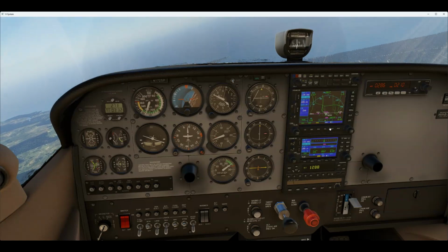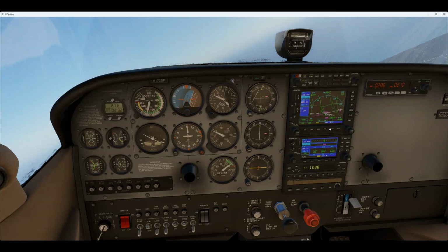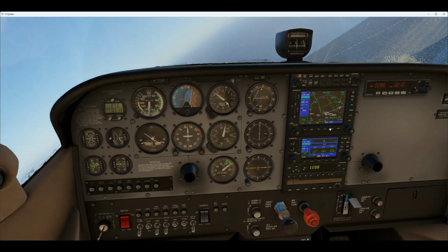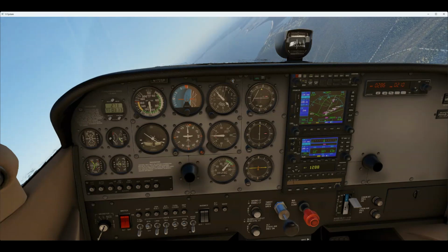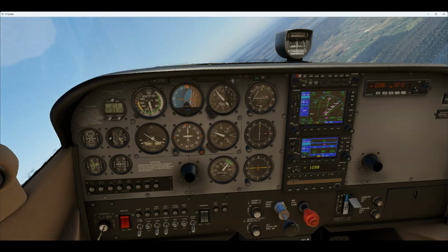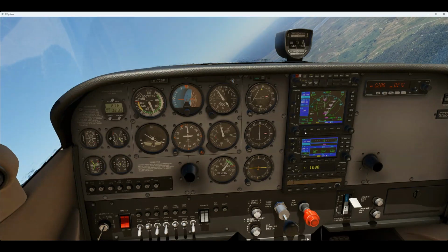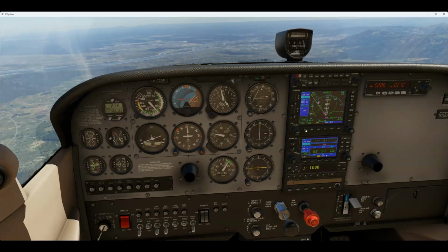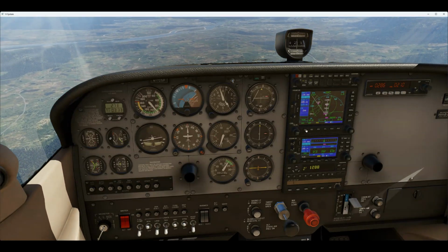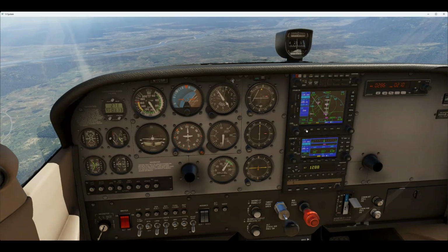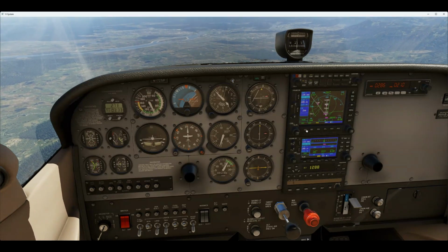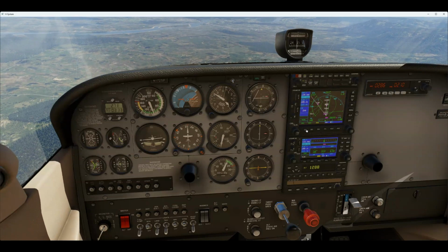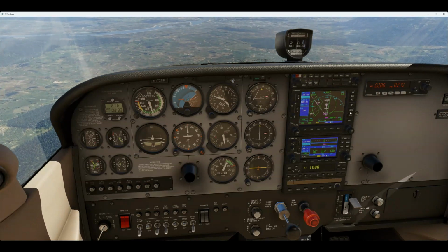So now we're kind of on that leg. We're facing the wrong direction, right? Our height's about right, 4,800. We can start descending down though. One thing to be aware of with these 430s and 530s is we need to be in the correct mode. At the moment we're navigating on the GPS. I'm now pointing towards the correct location. So now it's down there. I want to start reducing height, bring out the power. We're on a 172. We want to activate that approach again.